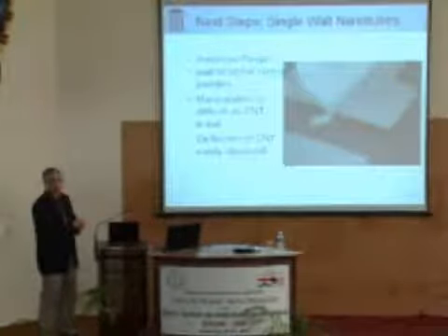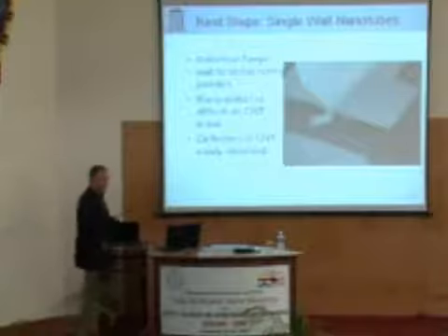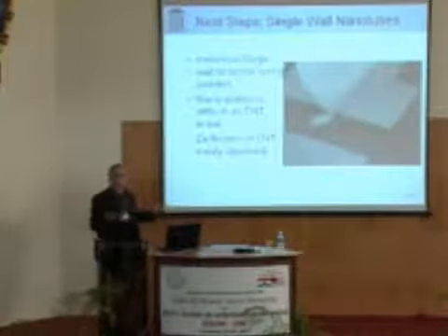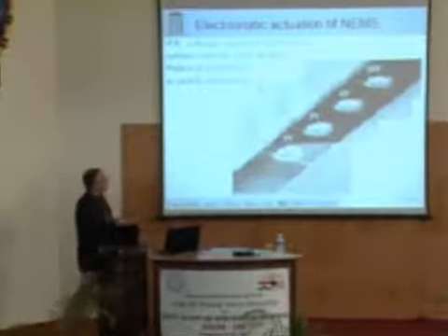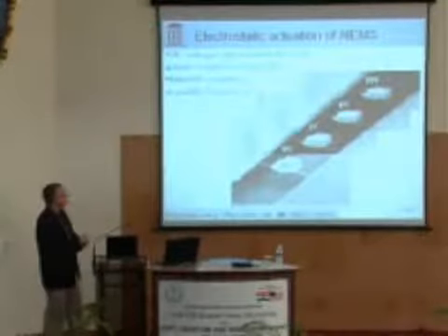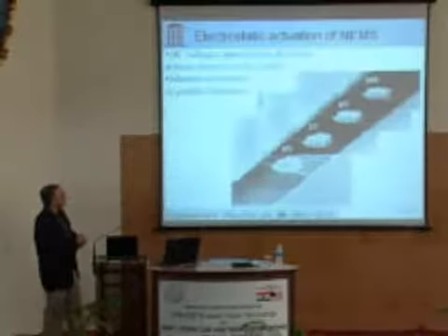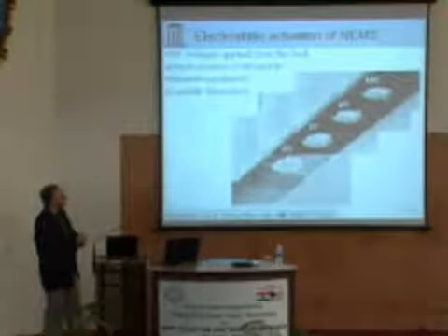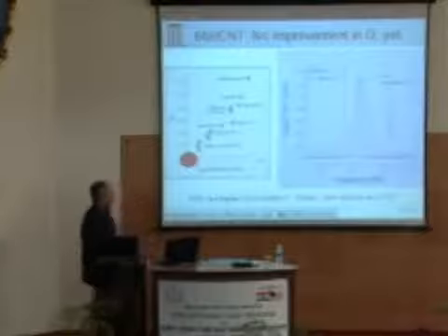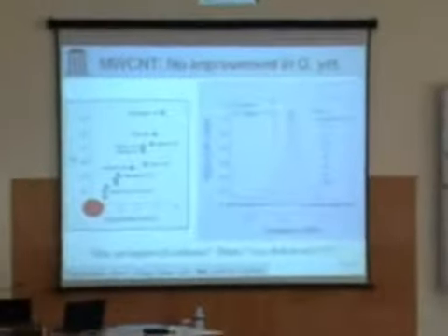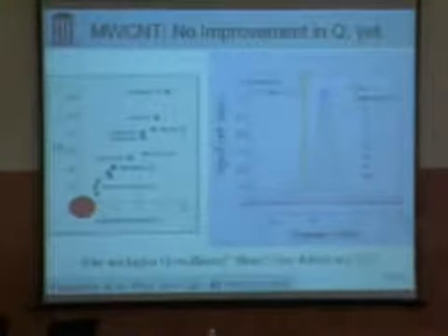So that presents real challenges for this technique here of using the AFM tip to press on this. And in fact, what we find is we start ripping our torsional oscillators up when we touch them with the AFM tip. So we have to go to, in the end, what we want to do anyway, and that is a completely integrated measurement using an electric potential applied to the device to actually twist the paddle. So here is applying a voltage to the back gate here, 0, 3, 6, 10 volts, and you can see the image change as we're twisting the paddle in this device. And we could actually get this multi-wall, this in particular is a multi-wall nanotube device, to oscillate. And we could observe the resonance frequency.